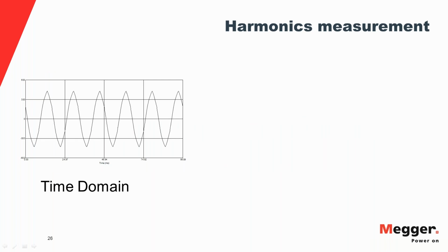So how are harmonics measured? There are two domains essentially. There's time domain and there's frequency domain. The waveforms that we saw so far during the presentation were all in the time domain. And the harmonic spectrum that you saw is what you get after breaking the waveform up into the different frequency components, essentially converting it into the frequency domain.